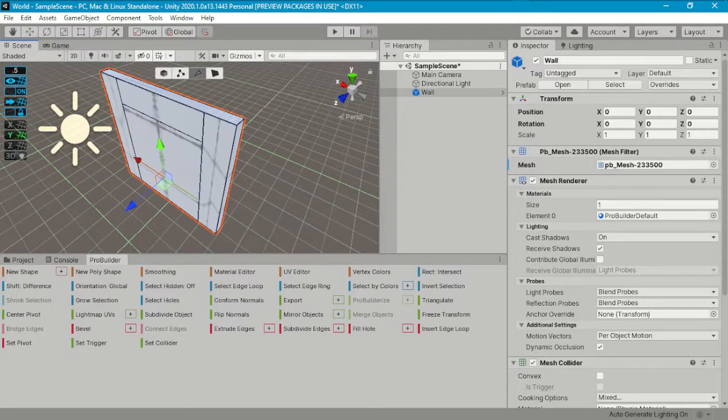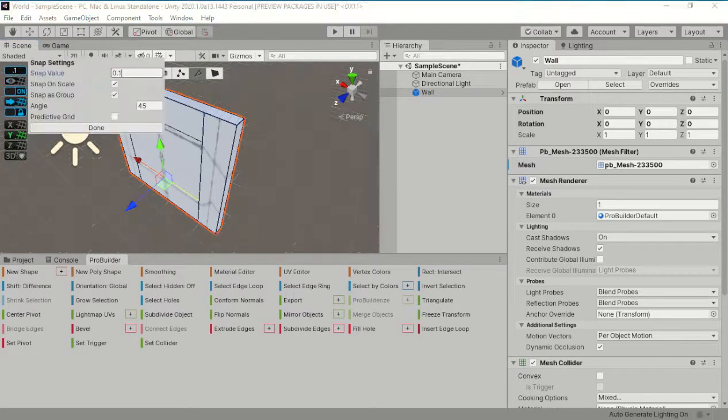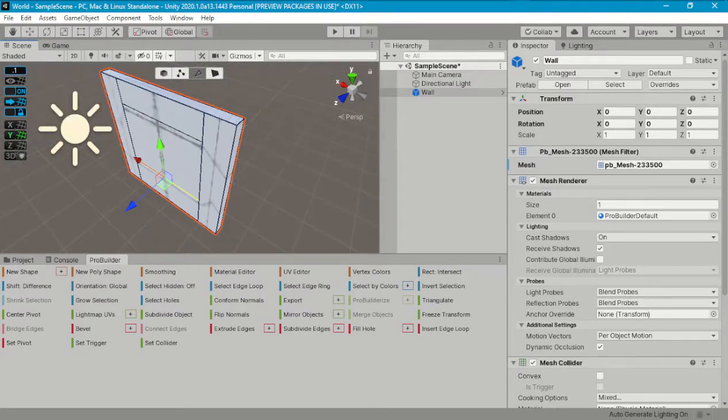As you may remember from previous episodes, the wall thickness is 0.2 meters. So, to ensure a proper snapping, we need to adjust the snap increment to 0.1. We cannot set it to 0.2 because we're working inside a cube of 3 meters per side with its pivot point located at the bottom center. In other words, 3 divided by 2 yields 1.5. Which, on a 0.2 meters grid, always leaves us either 0.1 meters short or 0.1 meters past the walls.